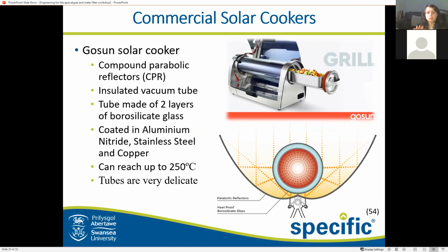So this enables the vacuum tube and parabolic heater combination to reach temperatures as high as 250 degrees C, as with the parabolic cooker, but in far weaker light conditions, and remain hot for long enough duration to cook due to its vacuum and insulated surfaces.